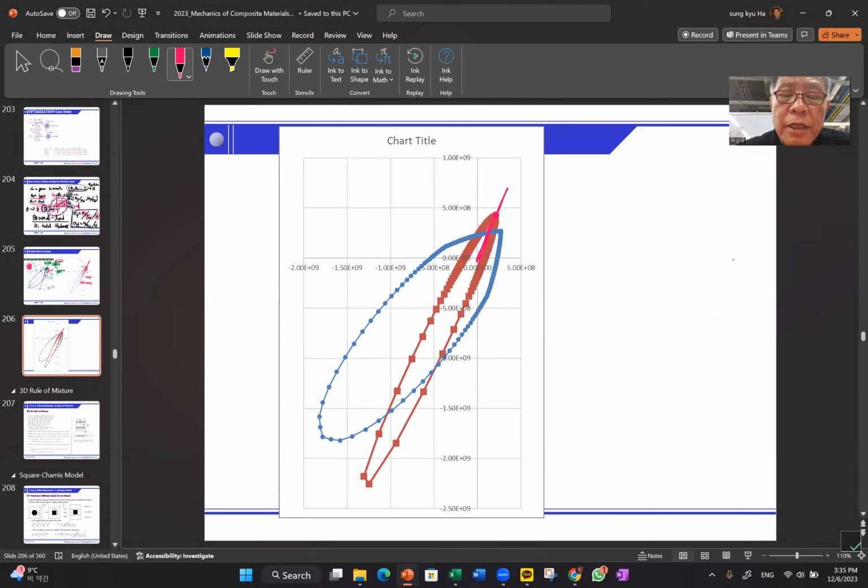So with the same number of plies, the biaxial 54-degree always gives us the highest strength. Now you can understand why this can be higher than others, which is very important.